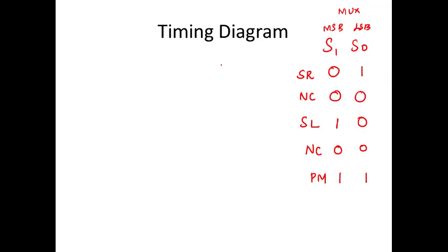And we have a clock, because whatever clock that we are giving for your shift register, based on the clock only your shift register is going to respond. Okay, so along with the input and with the clock, the rising edge of the clock. 74HCT194 has a positive edge triggered clock. Meaning for every positive rise of your clock, whatever input is present will be moved to the next stage, or if it's a parallel mode, to the output. Okay, so positive edge triggered clock.